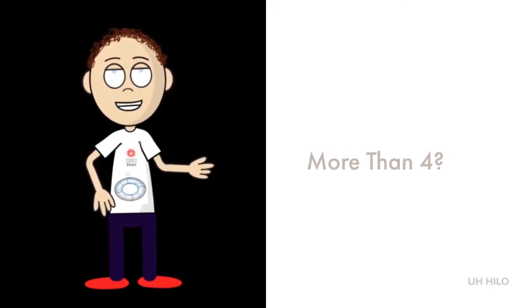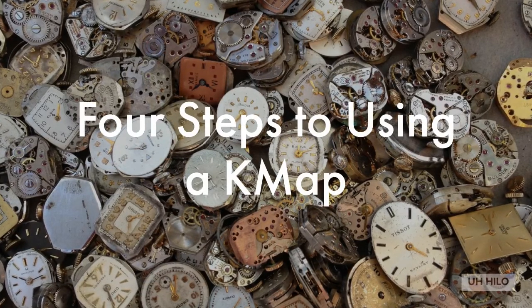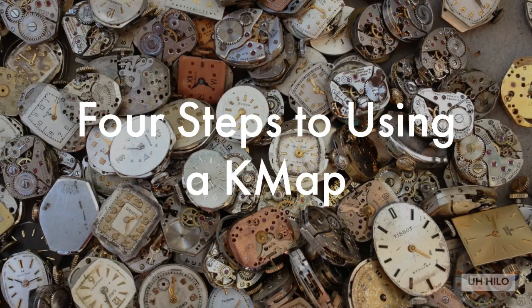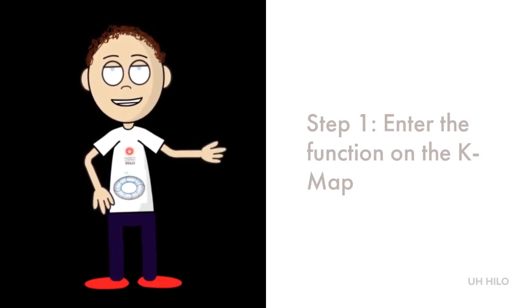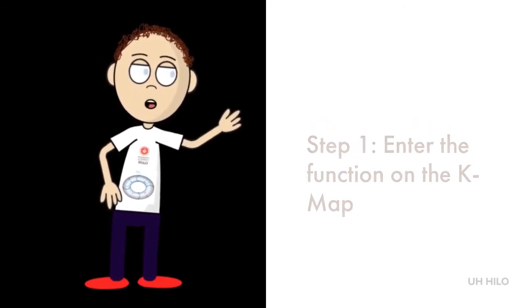same process to minimize. There are 4 steps to using a K-map to minimize a function. It's a little bit more confusing than doing the time warp from the Rocky Horror Picture Show, but should still be achievable. So let's give it a go. Step 1. Enter the function on the K-map. You can do this by using the truth table and putting 1s on the map for the active minterms.